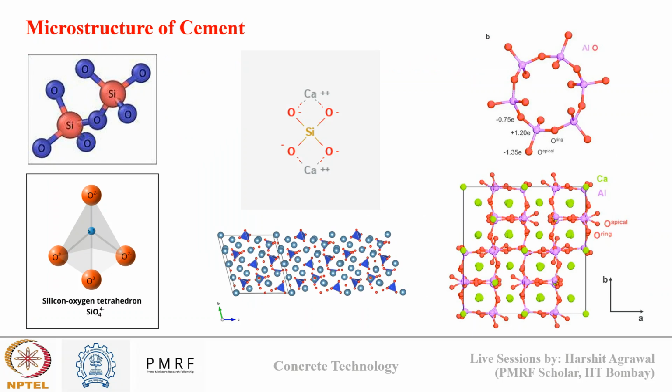First, why certain cement phases are formed. We talked about silicates and tetrahedra geometry, where the presence of unbalanced charges in the silicates leads to linkage and polymerization. Now, to balance these unbalanced charges, we discussed how C2S and C3S are formed. And similarly, we discussed aluminates, which also have tetrahedra geometry, and form C3A. And since C3A has an open cubic structure, it is more reactive compared to C2S and C3S.